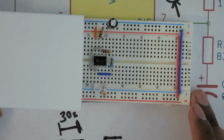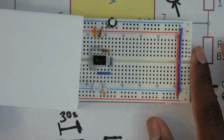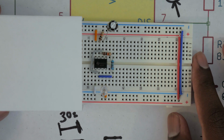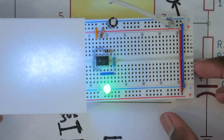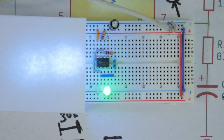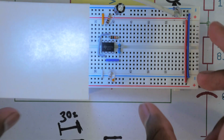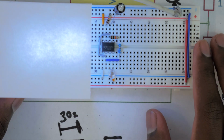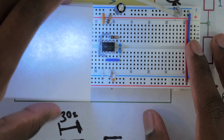So we can take a look at this circuit. This is the 555 timer. I built a little bit more, but I'm covering that up with a piece of paper now because I don't want it to distract from what we're actually looking at. Now we can plug this in so you can take a look at the timing yourself. We'll wait for 1 cycle and then get a timer on the screen. Alright, from there you can see that it was on for 30 seconds and off for 30 seconds. It wasn't exact, but it was pretty close, enough for what we need.